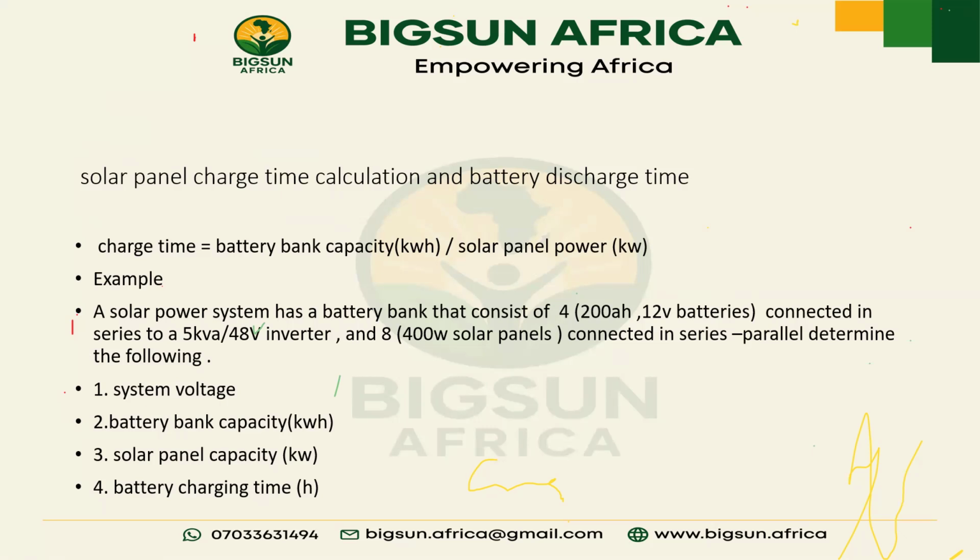So if you are using 8 pieces of 400 watts, in 3 hours our batteries will be full, if only the panel is generating up to 3.2 kilowatt. Exactly. So this is theory, because panels are not 100% efficient. In real life, when you are calculating this, you have to add the efficiency of the panel.